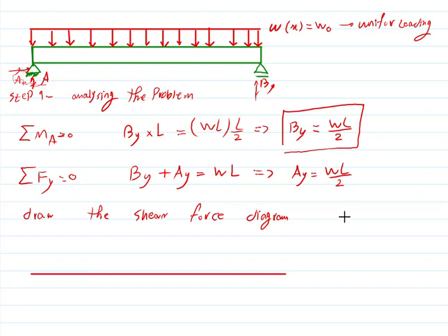So if I cut the beam at a distance x from the support, here x, and this is the load. Please tell me what we see here. My teacher always said, when you cut it, you will see it. And it actually works for beams. When you cut it, you free the forces, so you will see them.